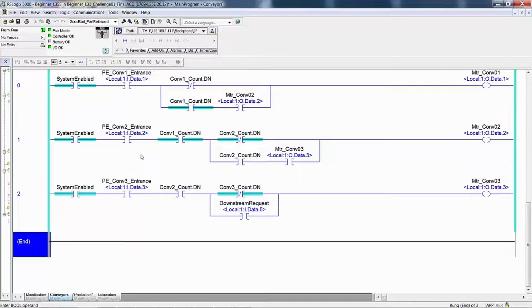Okay. We will operate the switches in this order: PE1 on, PE2 on, PE1 off, and then PE2 off. This simulates the parts blocking and clearing the photo eyes in that order: PE1, then PE2, then not PE1, and then not PE2. Think this through completely before you start. Visualize what you are doing. If you cannot visualize the process in your head without actually looking at it while you're programming, you will never make it as a controls engineer or a control system programmer.